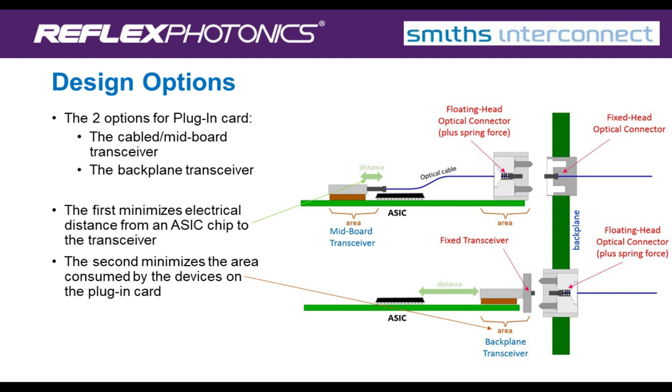Except in these two cases, optics is a fussy thing. You need to align these optical connectors. The fiber to fiber alignment has to be probably somewhere in the area of plus or minus 5 microns, which is down near 1/10 of a thousandth of an inch.